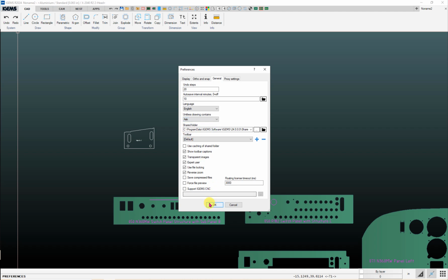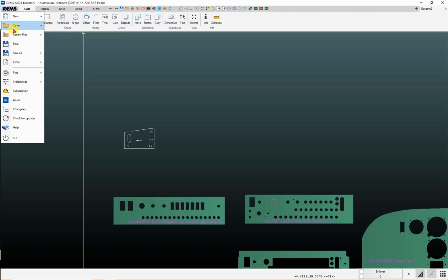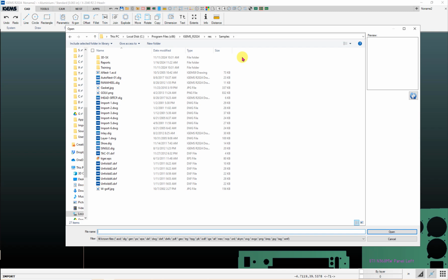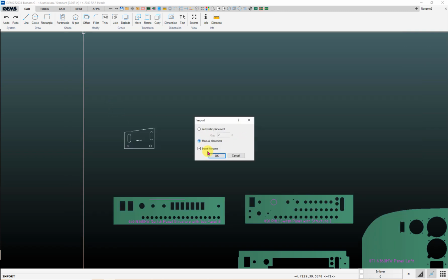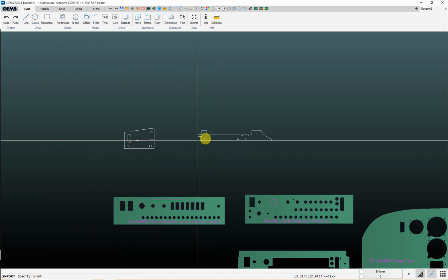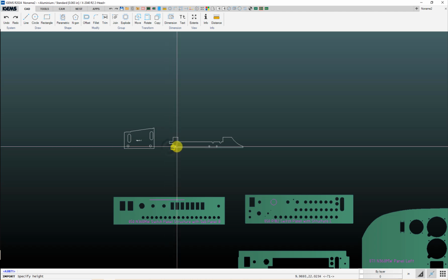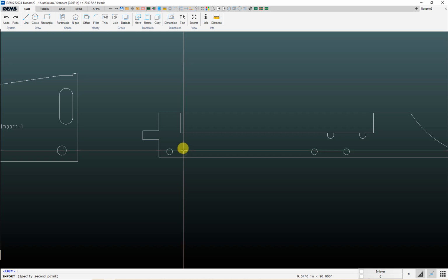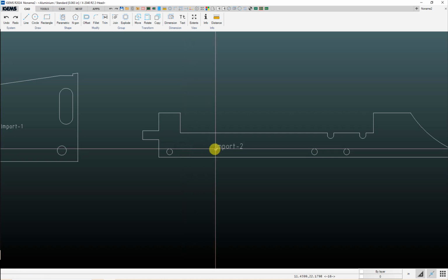If I do ask, import, let's take this one. So now each time I bring in a file, it's going to ask me what format it's drawn in. I'll tell it metric. It prompts me to specify point, left click, height of my text. In this case, again, I'll left click and move up a little bit, and left click and click that on there.